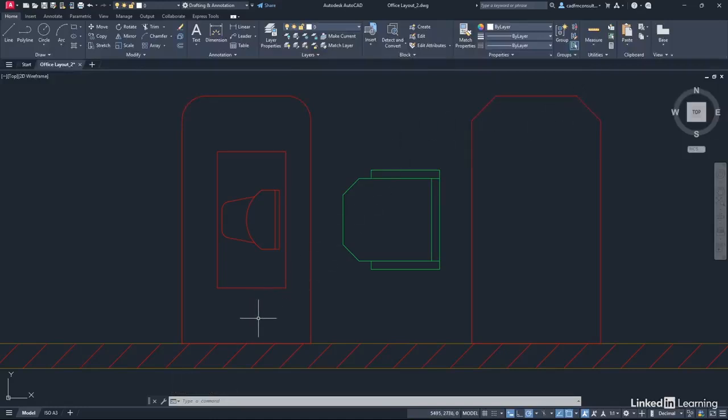Now you'll notice if you hover down here, there is a line segment that highlights. When you see it, left click on it, and it will have 3 grips. Click on the center grip to make it a hot grip, and just move vertically upwards. Can you see the polar tracking kicks in? Because you've got your polar tracking on. Now, when you see that polar tracking kick in at 90 degrees, type in 150, direct distance entry. Press enter, and you'll see it moves up that polar tracking line by 150. Just hit escape now to deselect it.